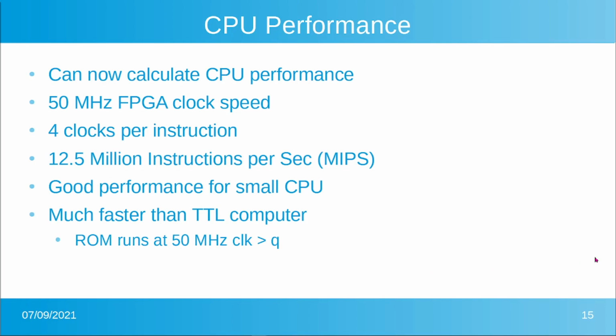And again, this is much faster than a TTL computer. I think Ben's maybe runs at a megahertz sort of speed, but the ROM easily can run at the 20 nanoseconds clock to output data, and the timing for everything in here should close at 50 megahertz.